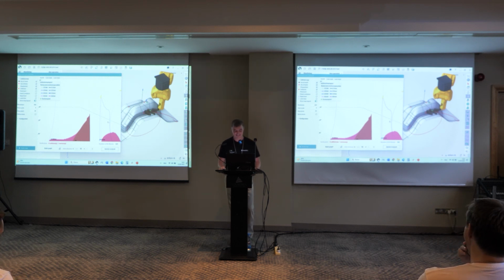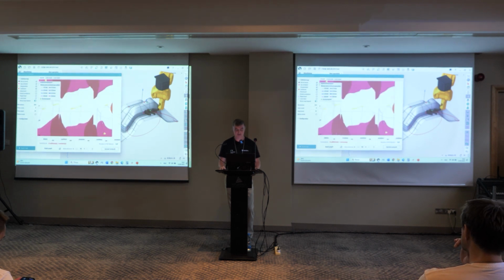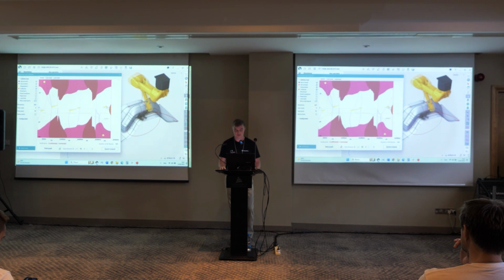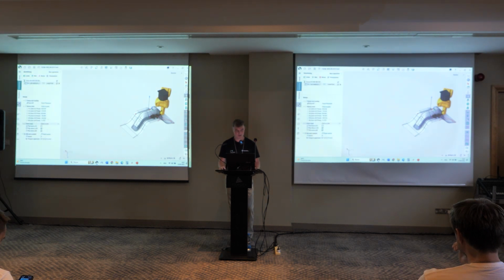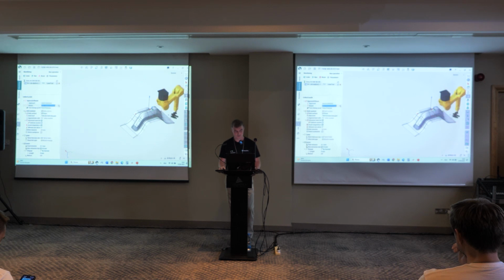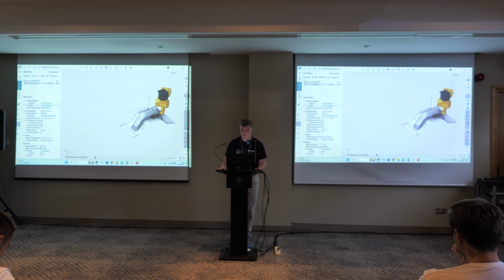Okay, and so I can, for example, edit the graph here. So verification says okay. I can update toolpath. There are no other turns right now, and let me maybe add the collision avoidance for approaches and returns, and we calculate toolpath.